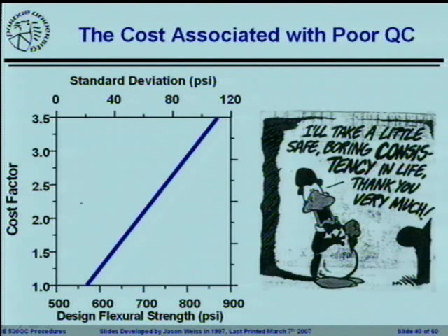One of the things that's a little bit tricky is everybody says, well, I can't get information like this. I don't know how I would get this. There's information in a book that exists, and some of you in the construction management world probably know what that book is already. Nobody's ever heard of Means? RS Means will tell you what the cost of different concretes are with different strengths, and you can get an estimate of what that would mean for an average type of mixture.